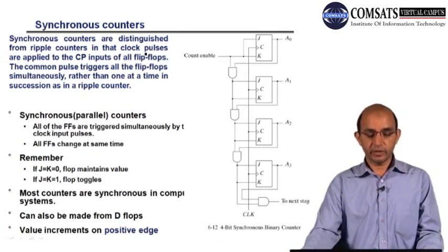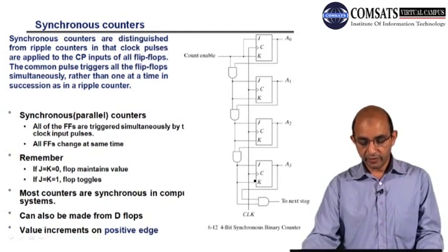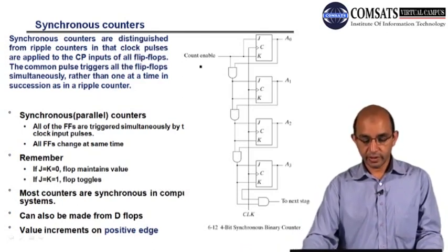So here we have the synchronous counter. The key difference is that we have the same clock. You can see that the same clock signal is applied to all the flip-flops. Here you can see that we have the count enable. This is another control signal. If you want to start counting, you have to make this enable. And this is the clock.